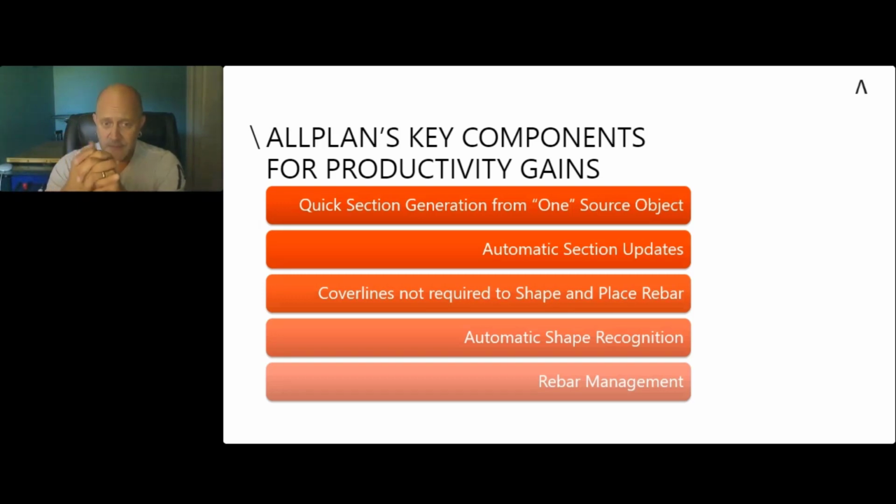One of the other key things is that in other software solutions you have to produce cover lines in order to get your bar shaped and placed properly in the proper position, the correct number of bars, et cetera. We don't require cover lines inside of ours. 99% of the time, a cover line is not required to place and shape rebar in here.